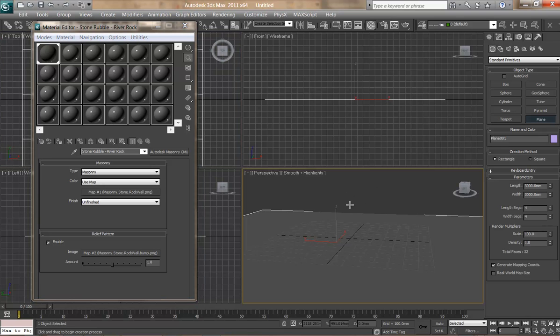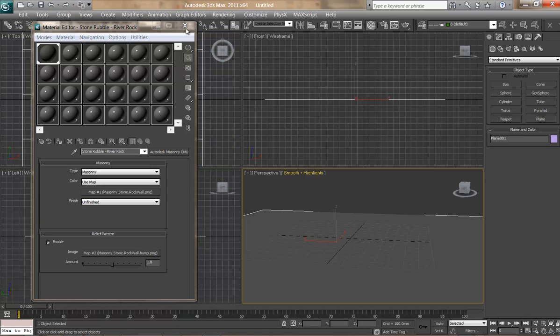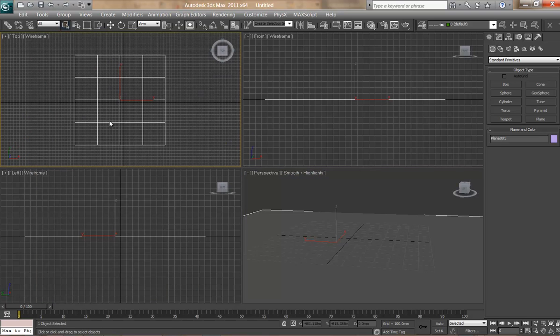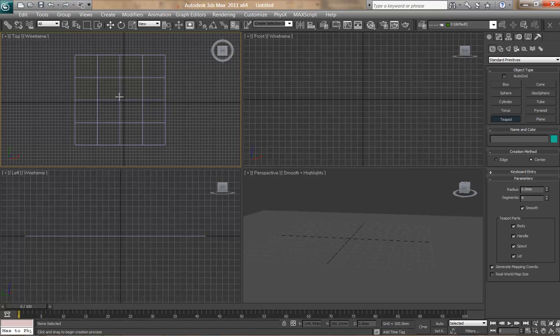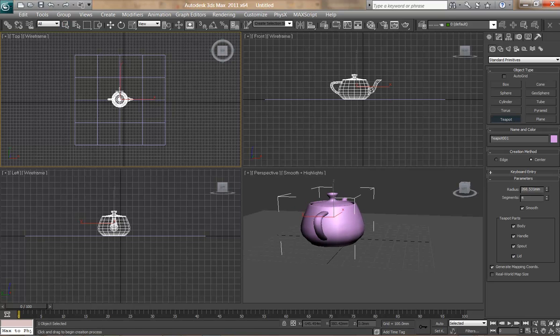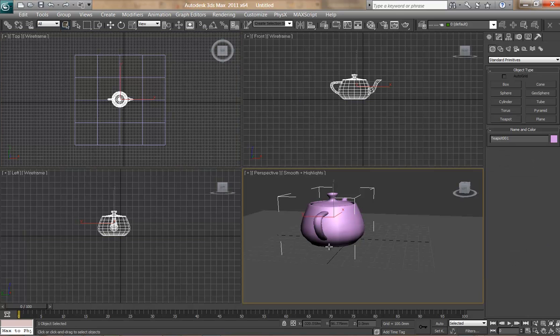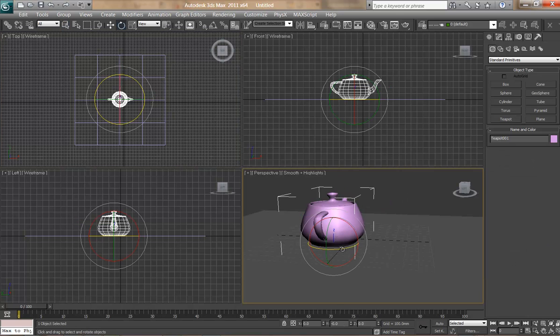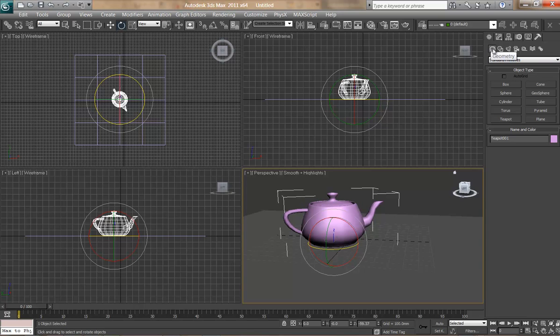Now, it won't do anything special just yet, but I'm going to then put a teapot onto it, just so we've got an object that can render. And this is a really good way of just testing things out. Do a very basic scene like this, and then you can try out different things. So teapots in Max are primitive, if I haven't shown you that already. So it's just on the geometry panel, the first panel in your Create panel, you find teapot, really easy.